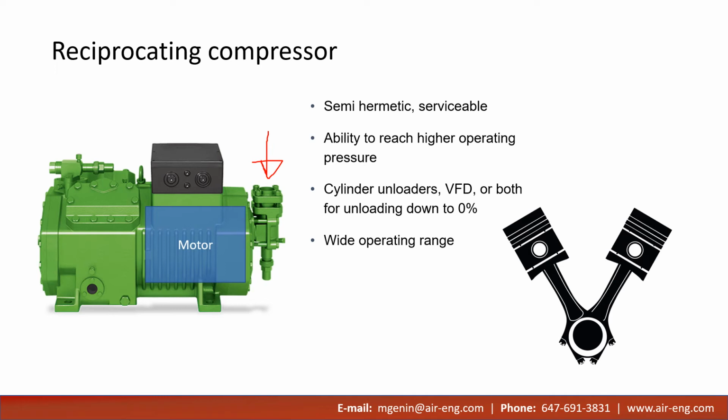We also refer to these as a positive displacement compressor. The easiest way to think of this is, imagine if we stopped the rotation of the compressor or the pistons. The refrigerant won't be able to go backwards through the compressor because it's always being blocked by the pistons and the valves on top of the pistons. So that's why I refer to it as a positive displacement compressor. We'll talk about other types of dynamic displacement compressors as well. And these reciprocating compressors are typically used for small 1 ton up to medium size applications, perhaps 80 tons out of a single compressor.